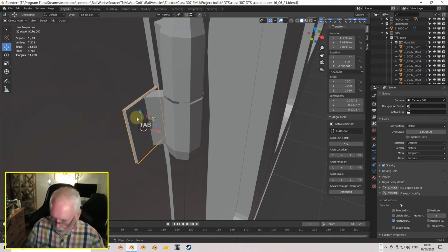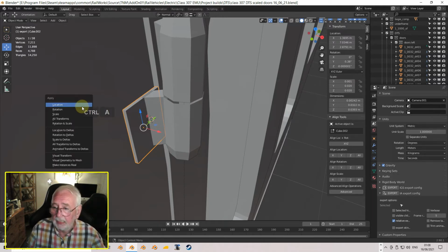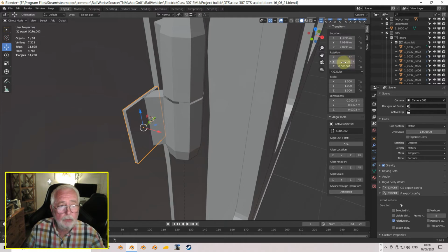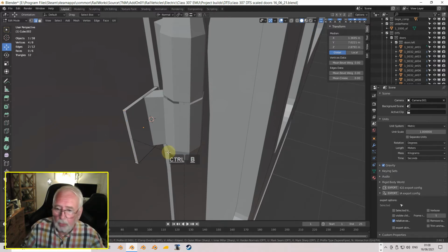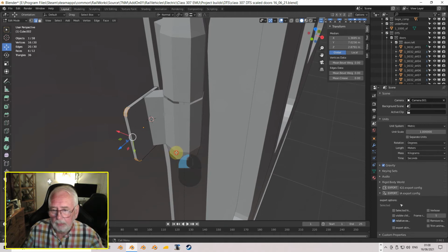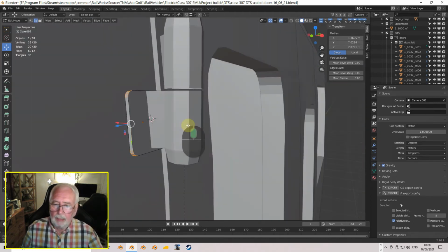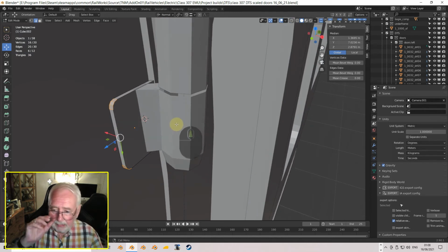Now just make sure the scaling here is 1, 1, 1, otherwise the bevel won't work properly. So reset the scaling, not the rotation, because we might want to use this rotation down the bottom or over the other side there. Okay, so that's set. Then let's just grab these two edges, okay, and Control B, and 1, 2, there we go. Yep, so that's our plate.